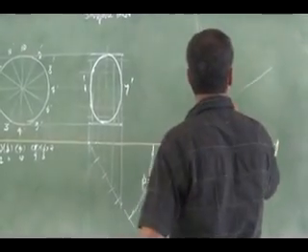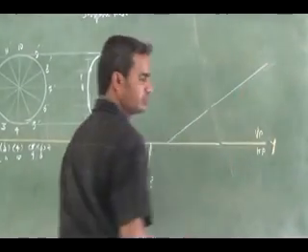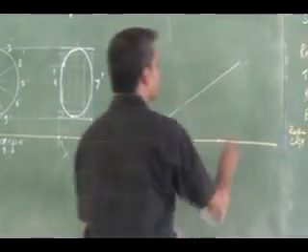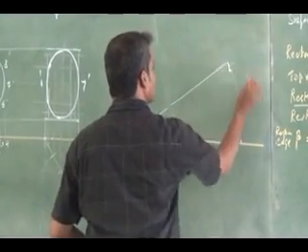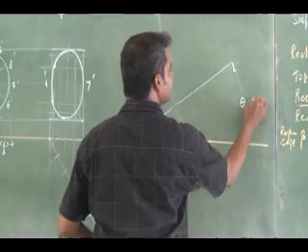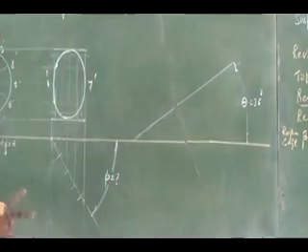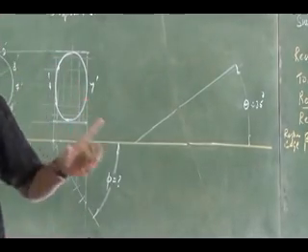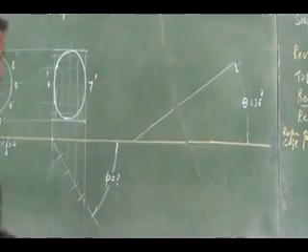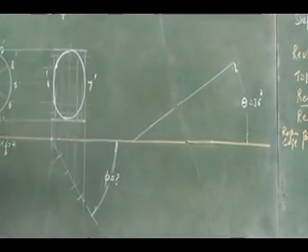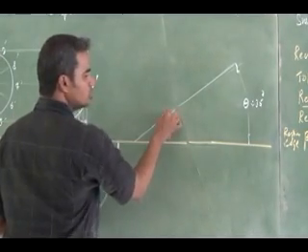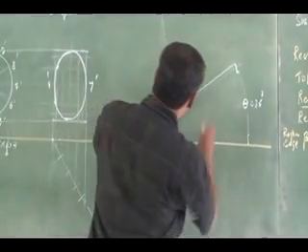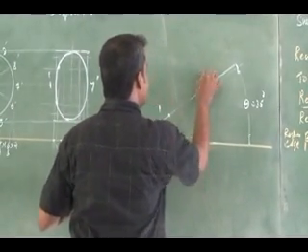So this inclination is 35 degree. Listen carefully. This is theta, 35 degree. To redraw this in an orientation, I need an apparent inclination with respect to HP. Apparent inclination is alpha. So what I am going to do is keep this 1 and 7 on this. 1 dash, I can measure this. What is this distance? Minor axis, 30. 30 mm I can measure it. This is going to be my 7 dash. I can mark it.